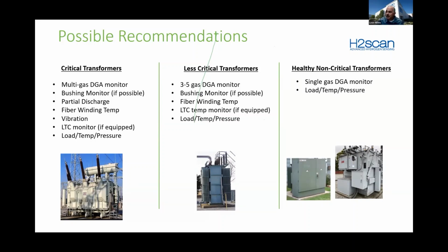And so we are seeing trends in the industry where people are looking at adding monitoring beyond just substation transformers to distribution transformers. Most people still aren't even monitoring those, but a lot of people have been monitoring those with hydrogen and moisture monitors for a long time. And as we get into things like distributed generation, wind and solar, and electric vehicle charging, distribution transformers are getting more and more overloaded.